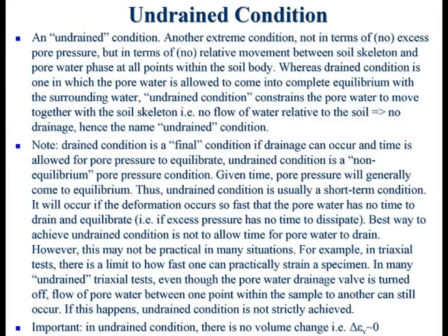Now the undrained condition is in a sense the extreme opposite. It is the extreme condition. And just now I talked about drained condition. All right? When you deal with drained condition, when you specify a drained analysis, you specify the pore pressure boundary condition. So you are able to say the pore water pressure inside the soil must be in equilibrium with the pore pressure boundary conditions like this.